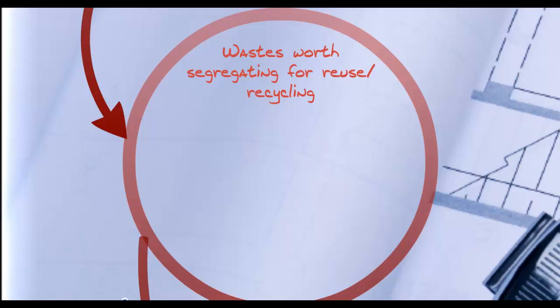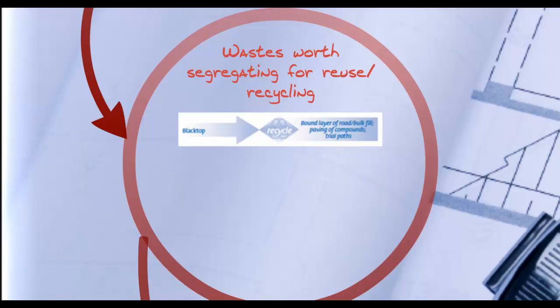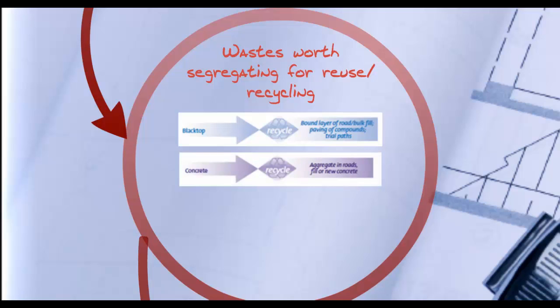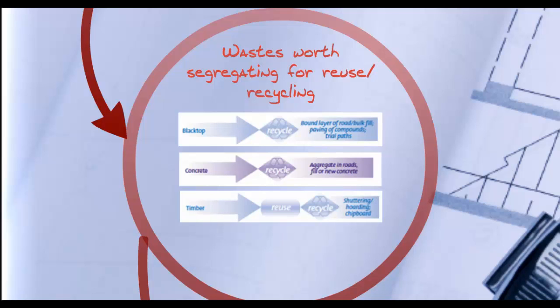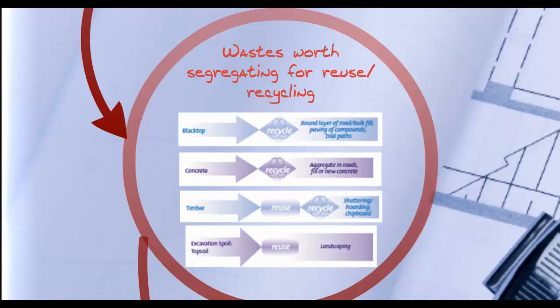Wastes worth segregating for reuse and recycling. Blacktop can be recycled, such as for bound layer of road, bulk fill, paving of compounds, and trial paths. Concrete can be recycled, for example, aggregate in roads, fill, or new concrete. Timber can be reused or recycled, such as for shuttering, hoarding, or for chipboard. Excavation spoil or topsoil can be reused in landscaping.